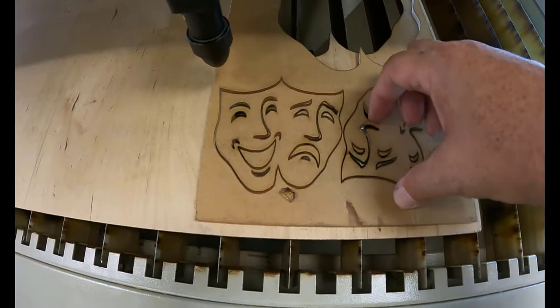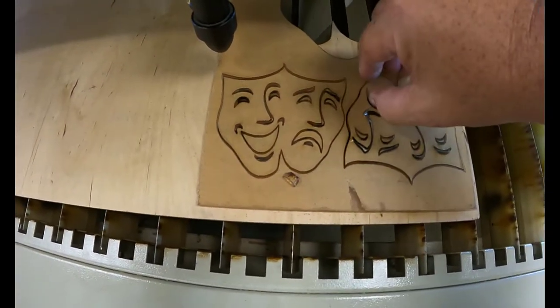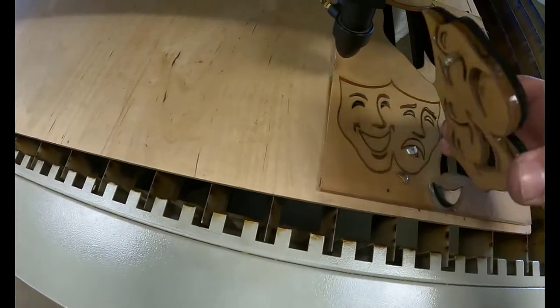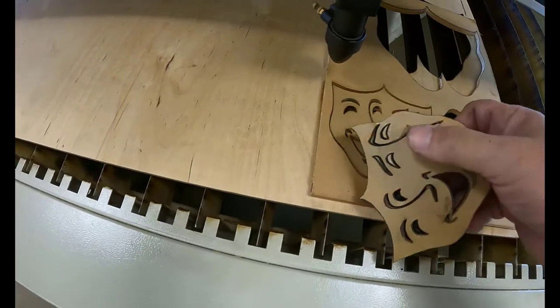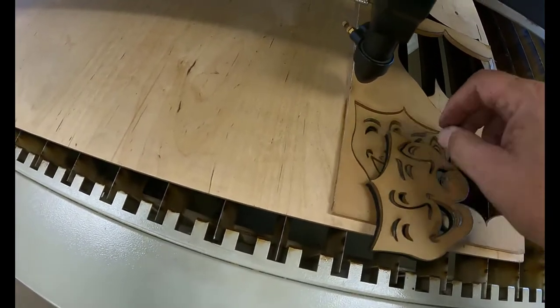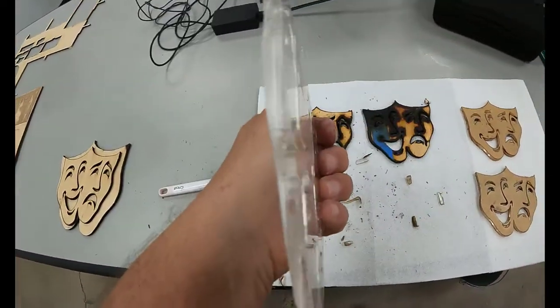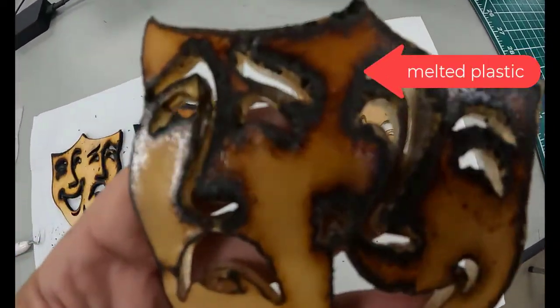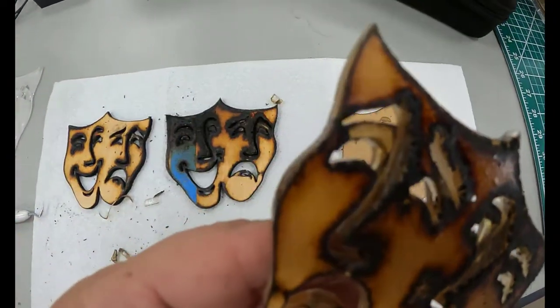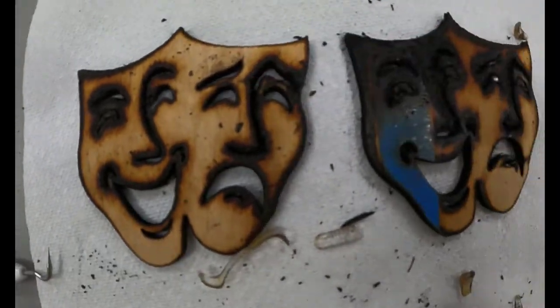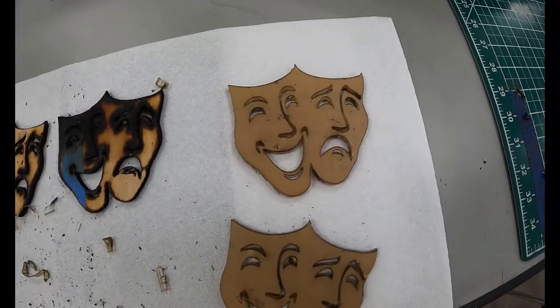Now the second test I tried was to cut the acrylic and the plywood at the same time. This turned out to be a horrible mistake. It didn't work at all. In fact, I shouldn't have done it because it was basically a fire hazard. The back side of the acrylic melted and caramelized. The front side of the plywood burned. There was an air gap between the two, which created a vacuum and a way for fire to be trapped inside, as opposed to being pulled through with the air handler and cleaned out appropriately.